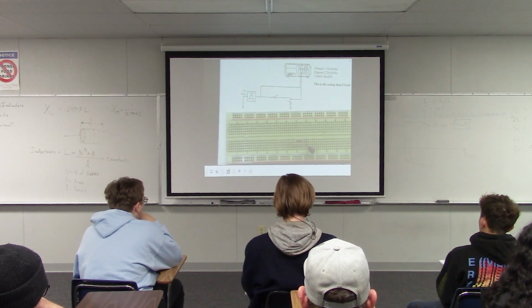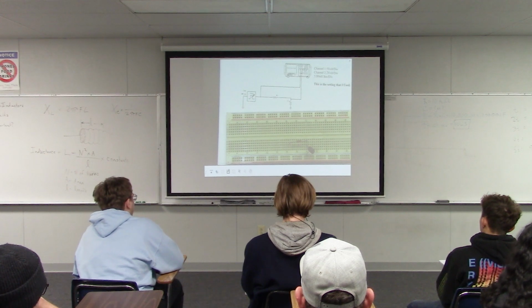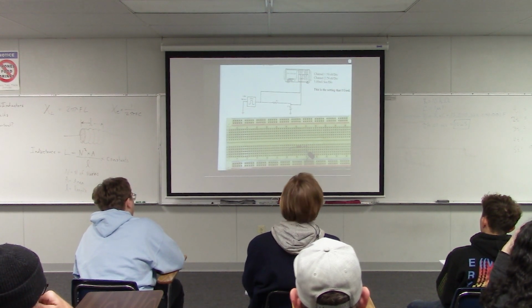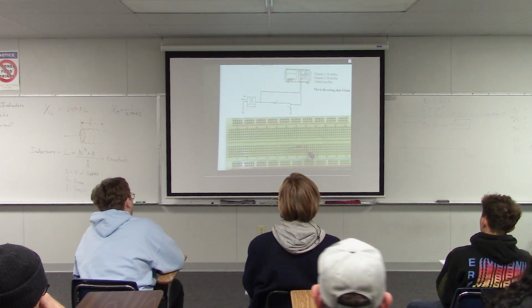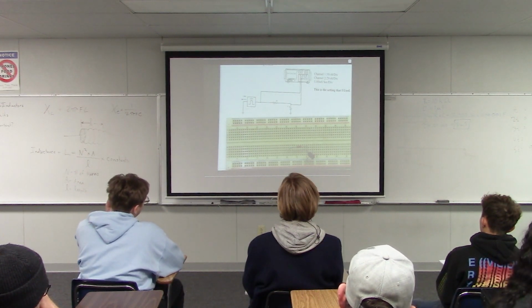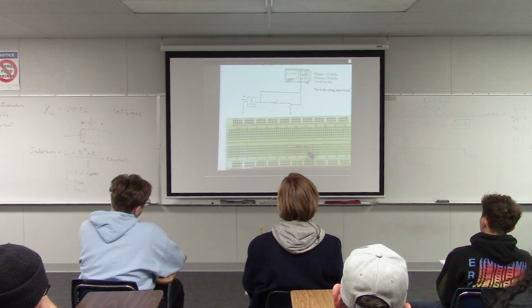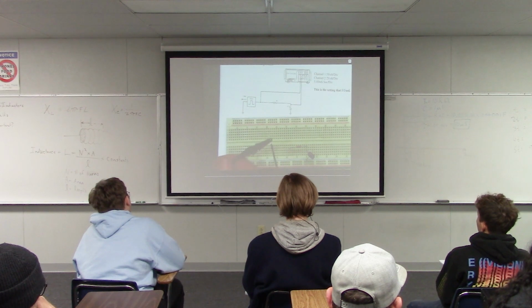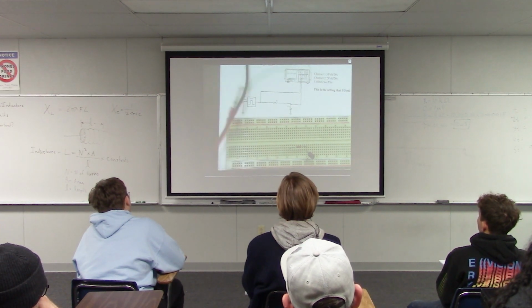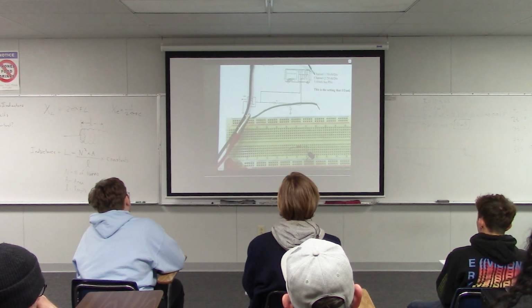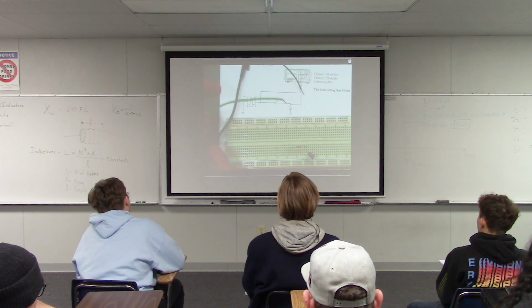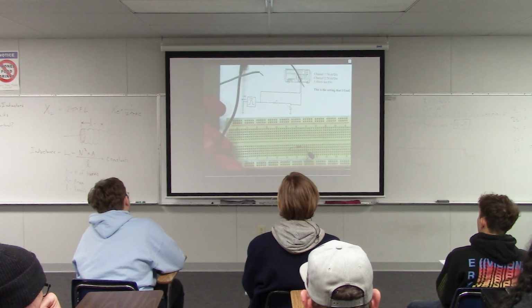Okay, so those are the components there, and then I want to attach my various signals. First of all, I'm going to attach the signals that come from the function generator. I'm going to take my function generator leads. I like to hook them onto little jumper wires because that makes it easier to attach them to the board.